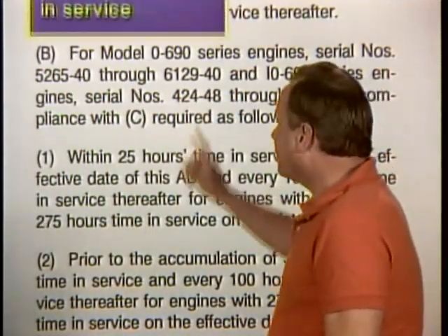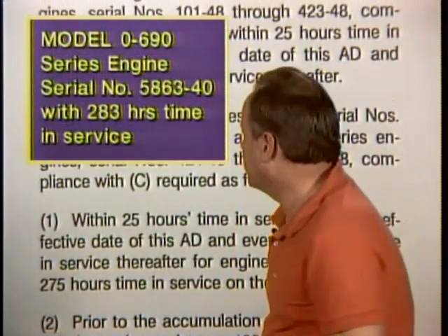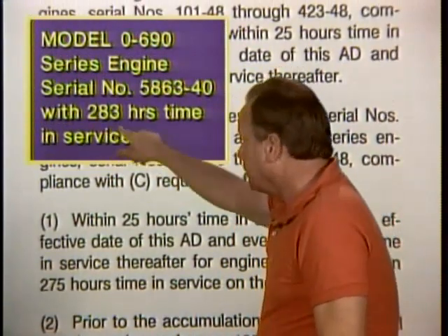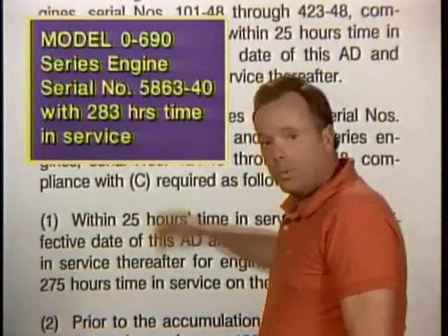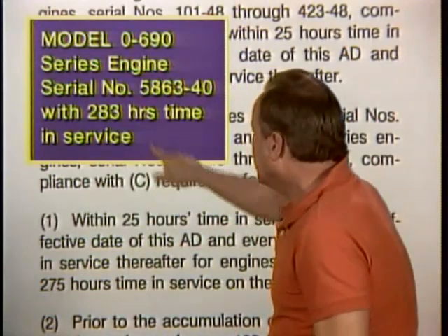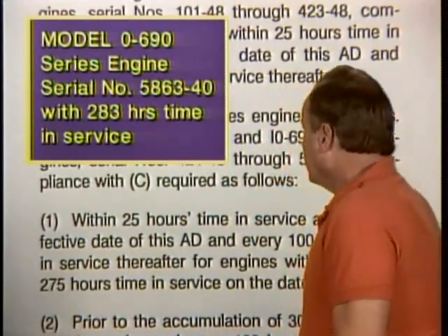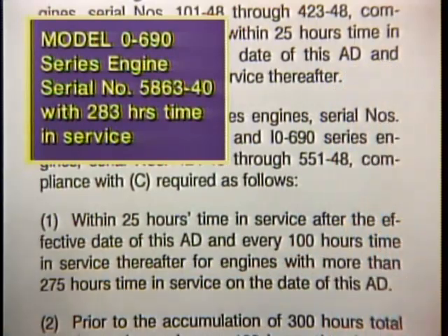Now, let's look one more time at our engine. Did we have more than 275 hours? Son of a gun, we did. We had 283 hours. And by the way, this is the way I would answer this on a test, is I would write this down and keep comparing it. So we did have 283 hours. It looks to me like we are going to have to comply with number one down there within 25 hours time in service. Let's check and see if we have to comply with number two underneath that.